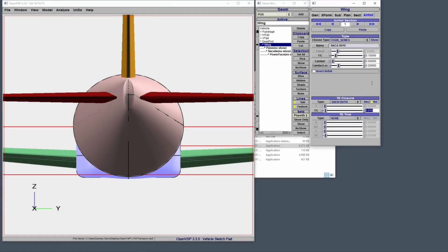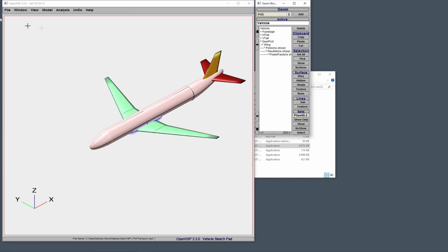Here, I've selected a value of 1.5% of the local tip-to-chord ratio for the airfoil section at the wing's root. I can repeat this for each of the airfoil sections that make up the wing part. Once I've updated the model to include blunt trailing edges on all of these parts, then I'm ready to export the model to a STEP file that can be read into Pointwise.